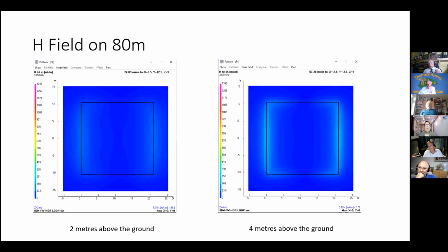So what you find, on VHF or microwave printed circuit board, you have a track on one side of the board, a ground plane on the other, and most of the field is contained between them. It is a form of transmission line. The same thing seems to happen if you have a radial over the ground: you will find a field all around the radial, but it is much stronger between the radial and the ground.